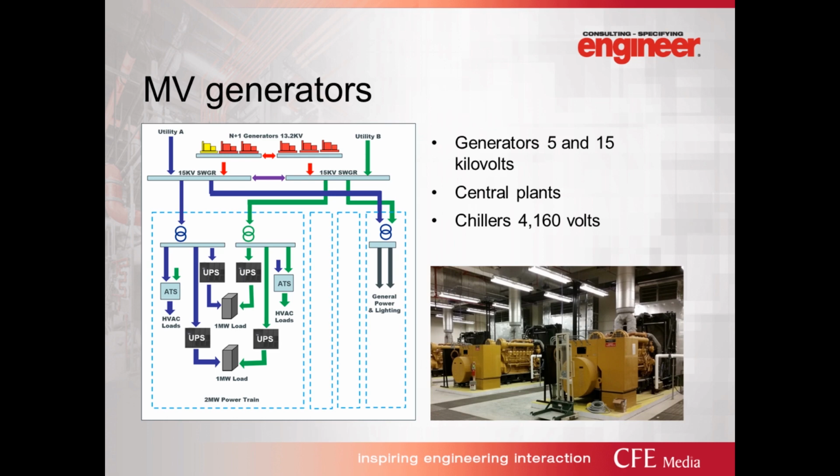Another thing would be chillers. You see a lot of chillers. If it's a big chiller plant for a campus at medium voltage 4160, again, you don't see chillers at 15 kV. It's usually 4160. And as Jane mentioned, now with chillers using a lot of VFD functions for efficiency, we're seeing a lot less 4160 volt chillers just because the VFDs are very expensive.